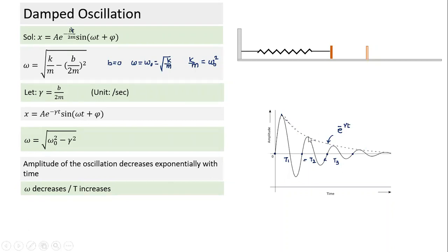Yes, Akash? So it still oscillates forever, but only the amplitude decreases. Right? Yes, but after some time, amplitude of oscillation goes to zero. Something we say in case of LR circuit. How much time does the charging take in terms of capacitor in an RC circuit? What is the charging time? Infinity. But still the major portion, 99.9% of charging gets over in a very finite time. So this also will continue for infinity, but amplitude becomes so small, it will barely be observable.